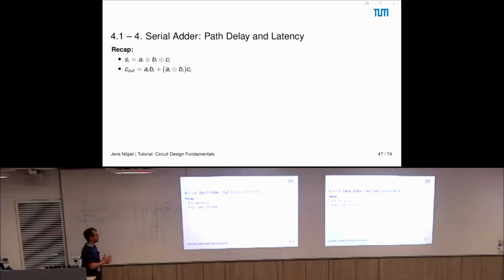So, a short recap: how do you do the addition? It's just XORing. How do you get your carry? It's the usual formula here. So A times B or A XOR B and C.